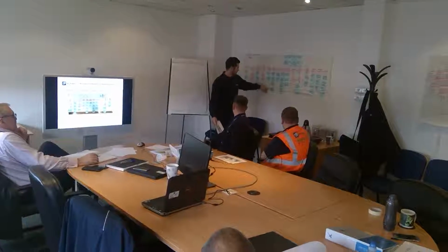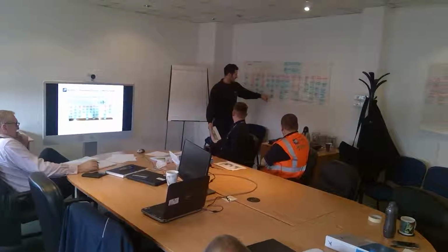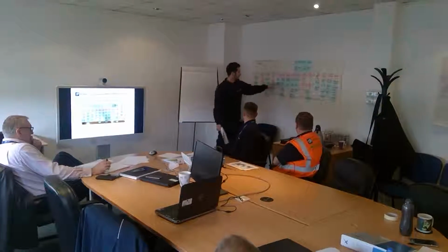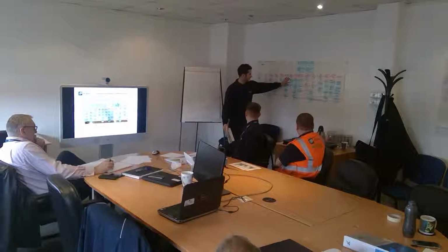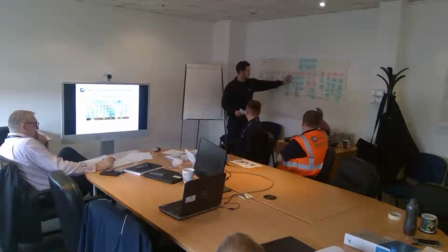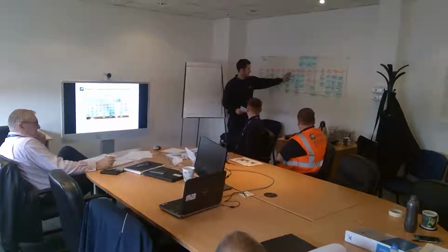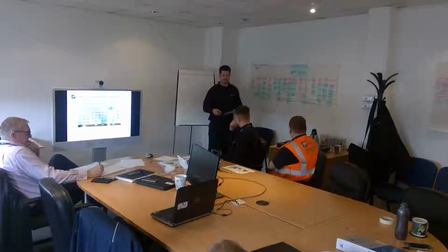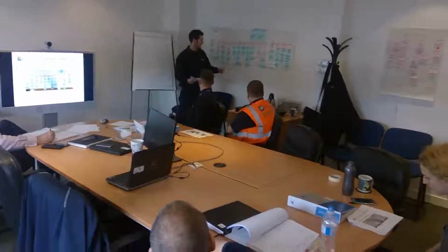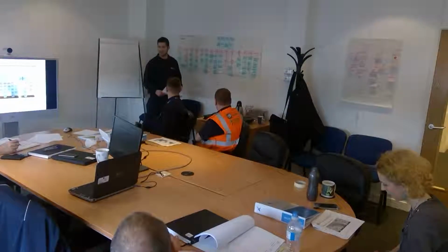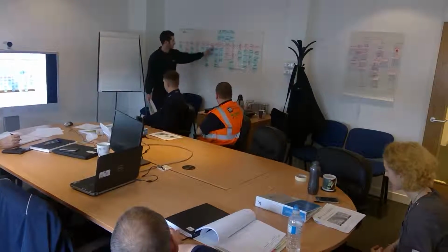Tooling issue, sorry, incorrect material calculation, again that goes back to under ordered and over ordered, stuff like that. Prepping process, it's pretty simple on stainless steel. It's a quick grind round with an internal disc. They cannot be cleaned, sometimes they're not cleaned properly, so if some grease and cutting compound gets left on it, that obviously then goes into affecting welder. Cutting error again, wrong length, wrong size pipe, wrong diameter, stuff like that.